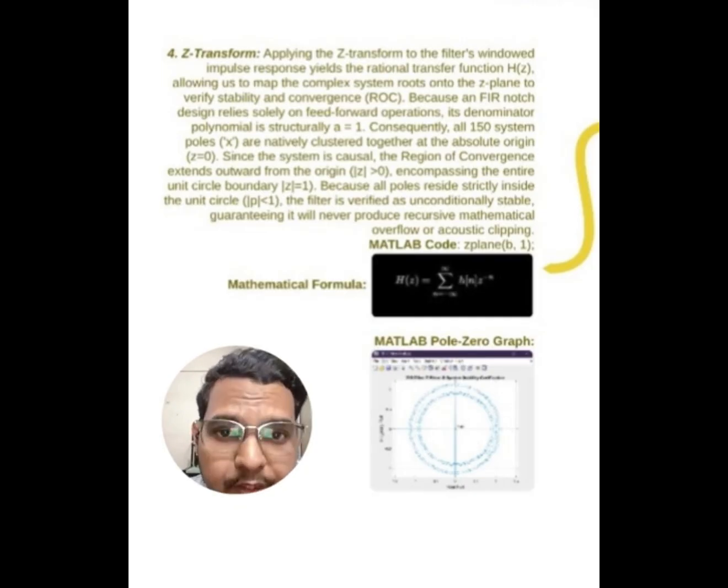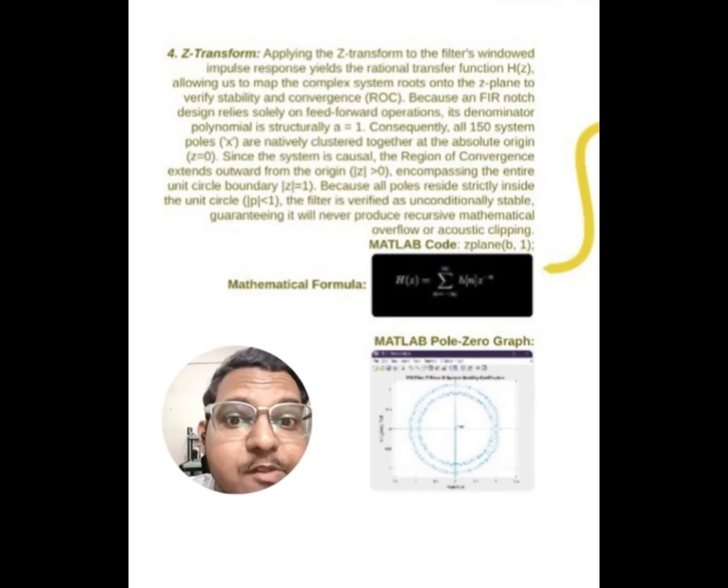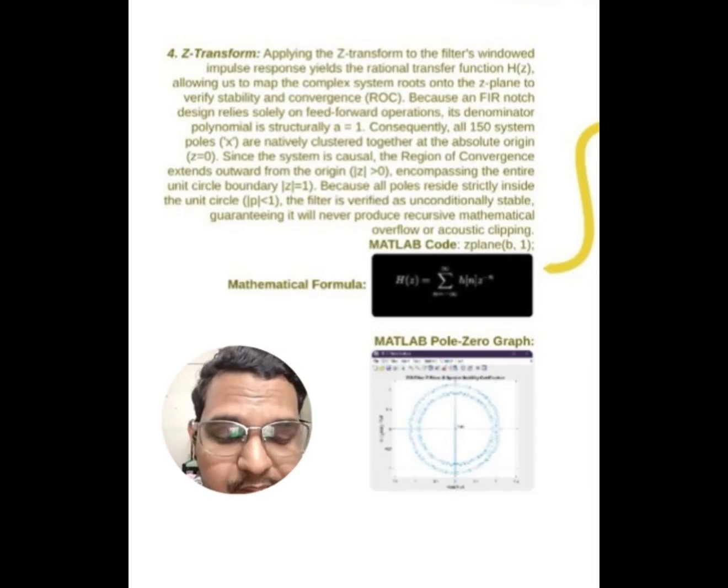Because it's an FIR feed forward operation, the denominator polynomial is structurally equal to 1. So all the system's poles are at the absolute origin, at z equal to 0. Since the system is causal, the ROC extends outward from the origin, so it encompasses the entire unit circle boundary, meaning |z| is greater than 0.